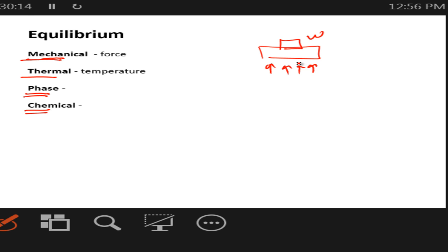The sum of the force is equal to 0. It's not accelerating. Hence, I have mechanical equilibrium. And I can get a relationship between the total weight of the piston. You'll also have pressure acting on top, pushing down, right? So the delta P from this side to that side is equal to the weight per unit area. That's from a force balance, mechanical equilibrium.